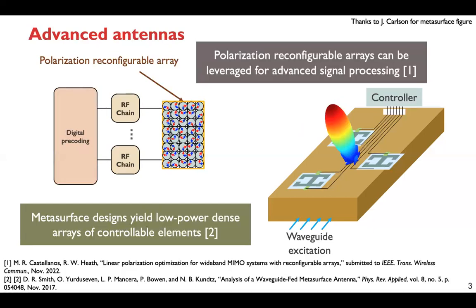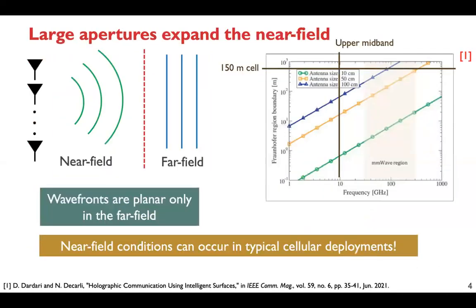On the right here, we're showing a gain pattern reconfigurable antenna that is implemented as a metasurface type leaky wave antenna. So on this design on the right, we actually have a number of unit cells, all of which are fed by a single excitation. But by adapting each of those different slots through an external controller, we can actually adapt how the antenna itself radiates energy.